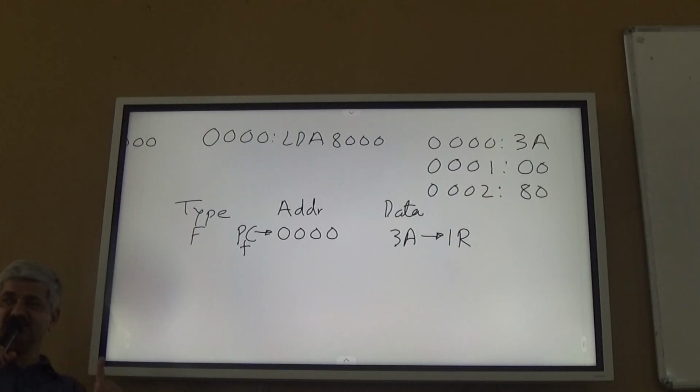The instructions are of different types. A few instructions contain only opcode. A few instructions contain opcode and one more byte of information. And a few instructions contain opcode and two more bytes. So 1 byte instruction, 2 byte instruction or 3 byte instruction. It must come to know how many bytes the instruction is. So it comes to that conclusion instantly.